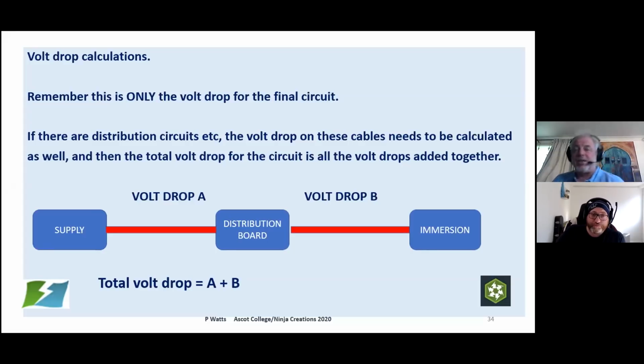The more tests you take, the values change. Manufacturers will say that. They'll say, give it time to cool down, because obviously as we pass those currents through, it heats up. And if we carry out loop after loop after loop, or constantly carry out IR tests, they're going to get warmer and they're going to start having off accuracy.